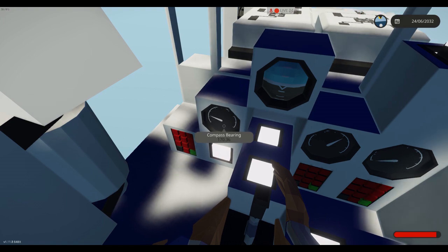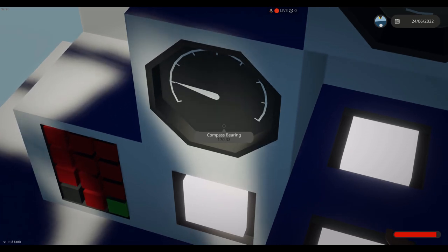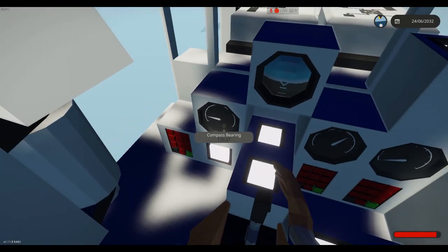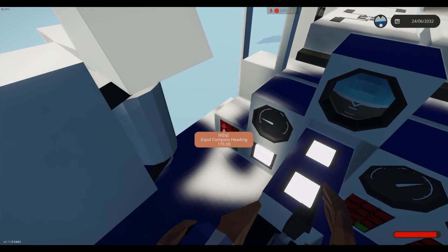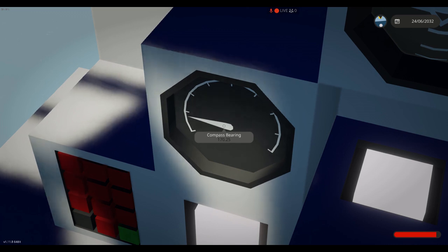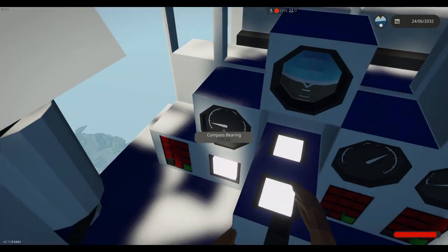So as you can see, this is quite ideal so far. We are very slowly getting towards 170. You can see our decimals just barely moving lower and lower to get to 170. I'm going to wait for it to really get all the way there and stop moving, but it doesn't appear like I'm going to be getting any detrimental overshooting, which is exactly what we want. We never want an overshoot of more than half a degree. Sometimes it's okay if it's like 0.60 or 0.50 degree, but you would never want a full degree overshoot.